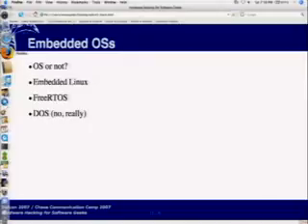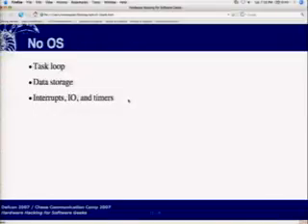Then the next step up is, of course, a real-time OS or embedded Linux or eCos, which is a free real-time OS, and then I think Abe had something to say about DOS. DOS is not a real-time OS. However, when your process is running, DOS is not doing much itself. It's not hard real-time. You wouldn't, I don't think, want to use it in anything that people's lives depended on. But the band The Sisters of Mercy used it as a drummer for a long time, so if it's good enough for them, it's good enough for me.